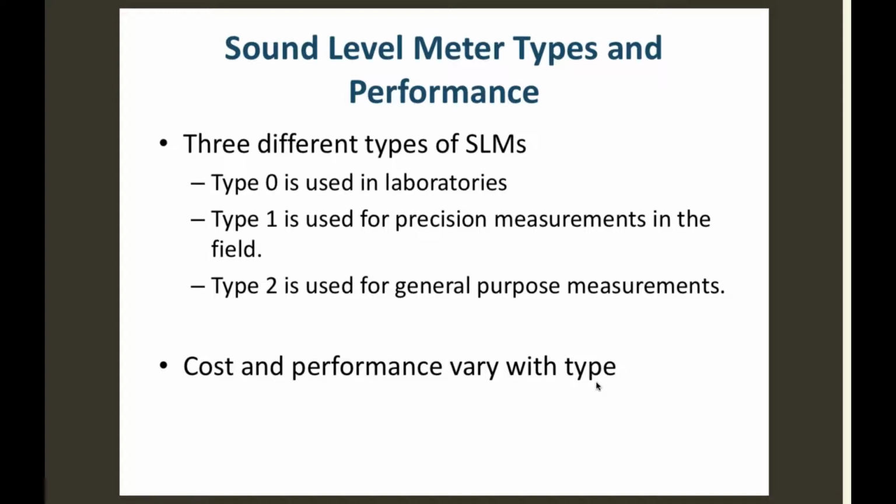So if I want to start doing a survey in here, what's the first thing I have to do with this thing? Bingo. Thank you very much. Okay, excellent. I have to calibrate the thing. So we have devices for calibration. This basically is a little sound production device. If you read somewhere on it, right down here, it says that it produces 114 decibels at 1,000 hertz. So when I turn this switch on, can you guys hear that from back there? Right, when I turn the switch on, you can actually hear this making noise.